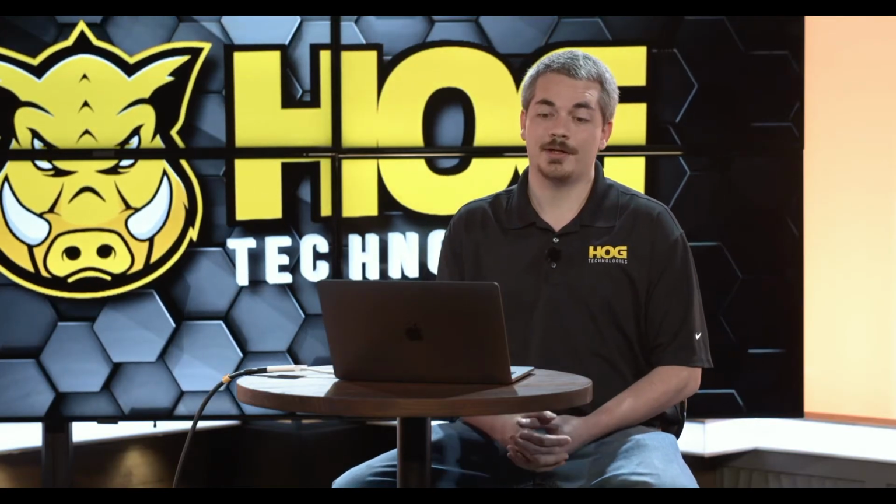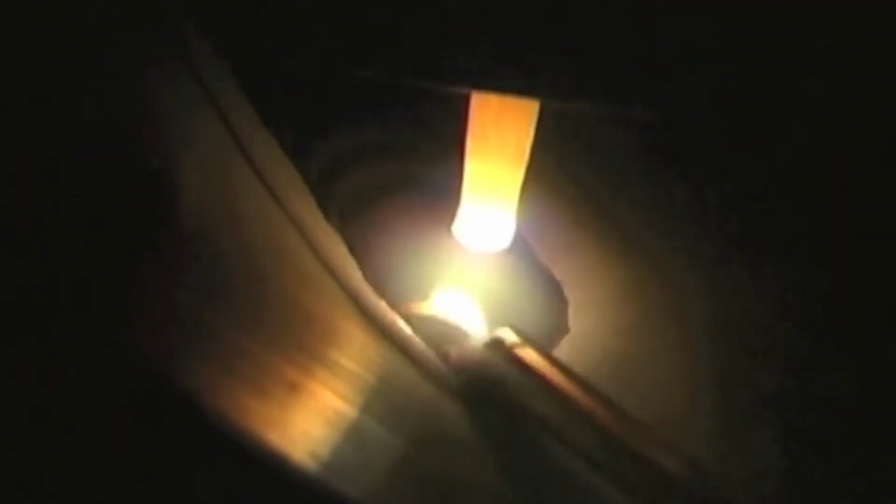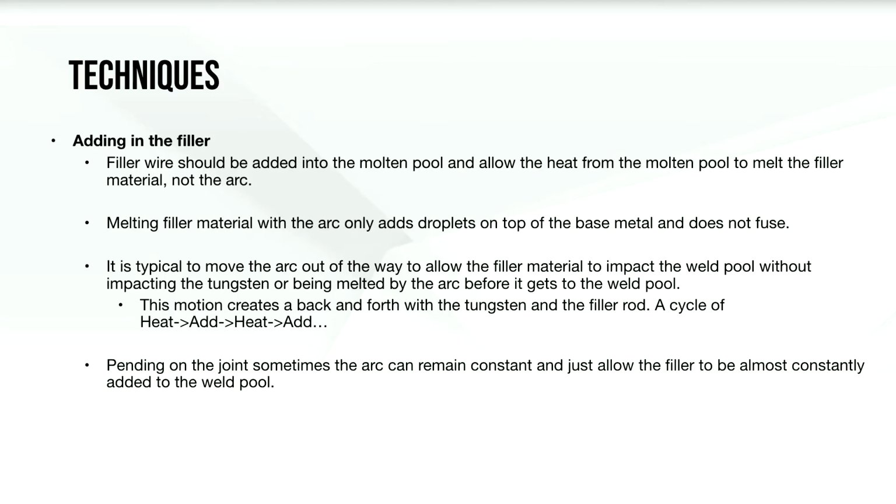When adding the filler metal, the filler wire should be added into the molten pool, allowing the heat from the molten pool to melt the filler metal, not the arc. If you're melting the filler material with the arc, it adds droplets on top of the metal that are not fused in, and you're literally just dripping metal on top of each other. You're not fusing it in. Always add the filler to the molten weld pool.